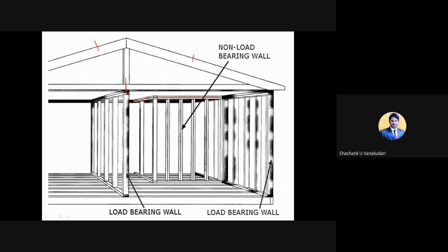Yeah, and no other advantages will be there, just to maintain certain gaps or the dividing portions within the room sections they have provided, and certainly they are not going to take any additional loads on top of that. And here also you can see the load bearing walls. Whatever the roofing load which will come will transfer to these load bearing walls, and then these load bearing walls later are going to transfer that entire load to the floor or else to the ground.